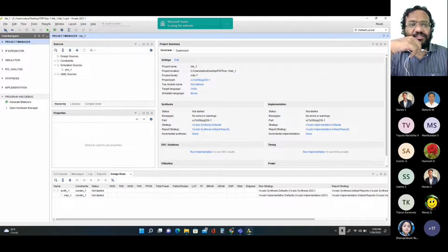This file needs to be dumped onto the FPGA. Depending on this file, the FPGA will be configured and the hardware circuit will be realized using the onboard FPGA resources, which we technically call the FPGA fabric. On that fabric, the circuit is being realized.